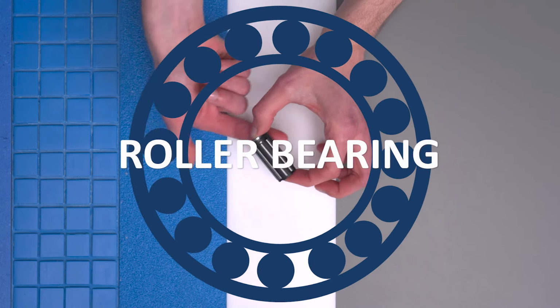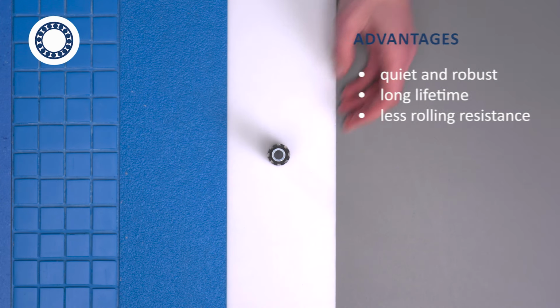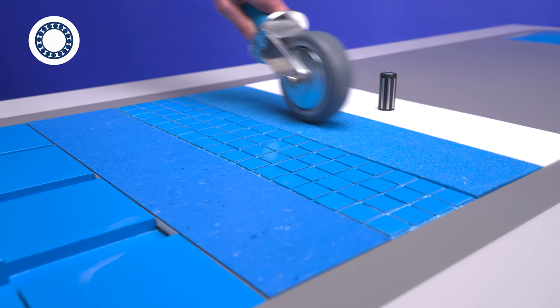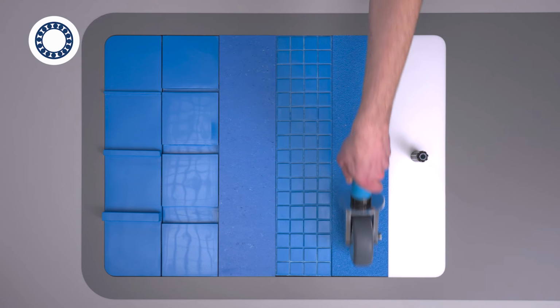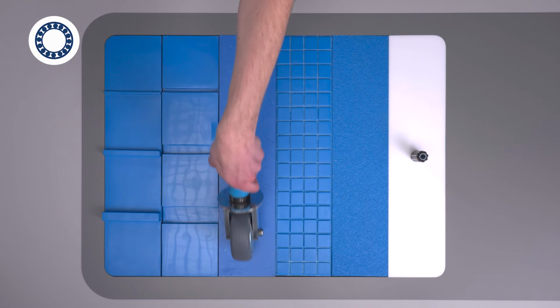Roller bearings have a high load capacity. Because of the outer circle, heat can be distributed better. Roller bearings are quiet, robust, and have a long lifetime. They have less rolling resistance than plain bearings and therefore slightly better maneuverability. Most of the time they are used for equipment which is moved at low speed, like walking speed.